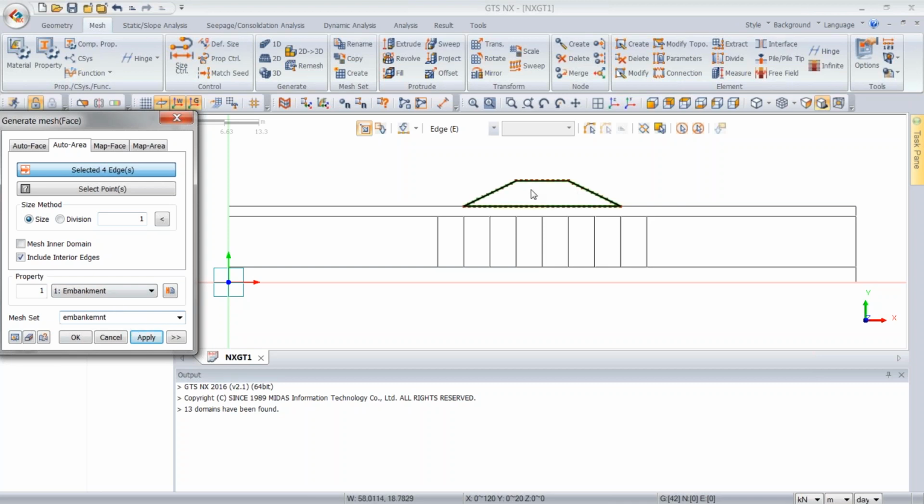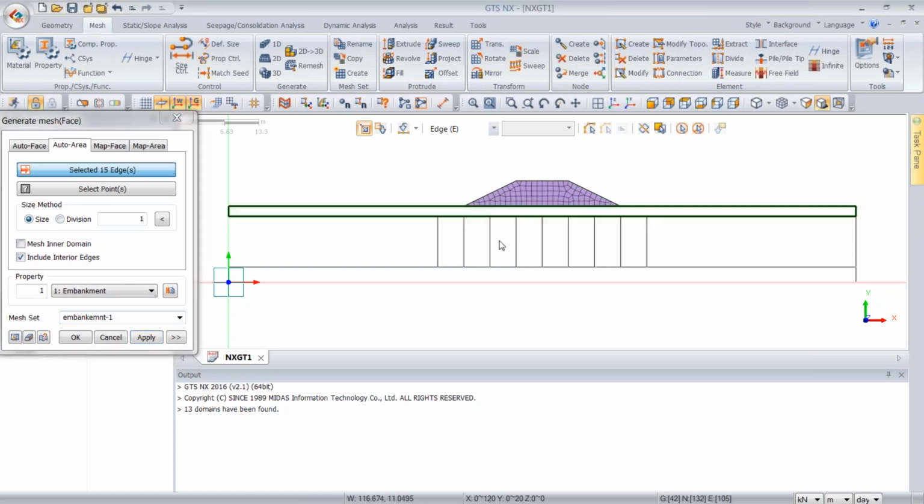I can preview the distribution of the size of the elements with this command here. And so that looks like a good size for me, but it's also a good practice. And if you're not quite sure what size of elements you're using, you can always preview it beforehand. But we'll just leave everything here at 1. So basically it's a 1 by 1 element. This will be the first layer. So we could just call it AS1. Remember, it's the first layer of sand.